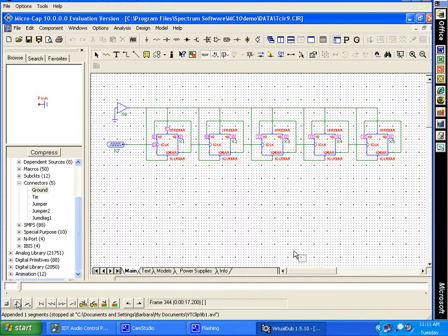Tutorial 9 is a divide-down circuit. Each 7474 TTL D flip-flop is wired to change state on the rising edge of its clock input. It means the Q output of each flip-flop is 1/2 the input count clock rate.